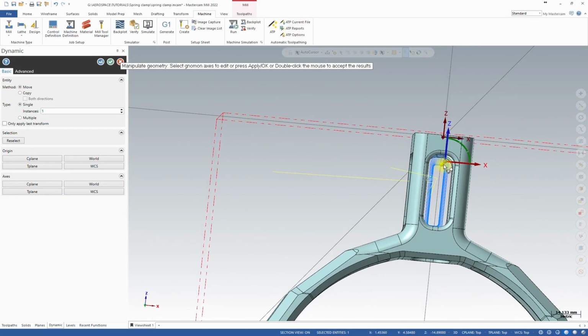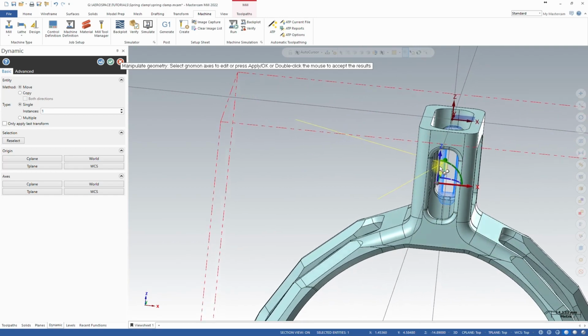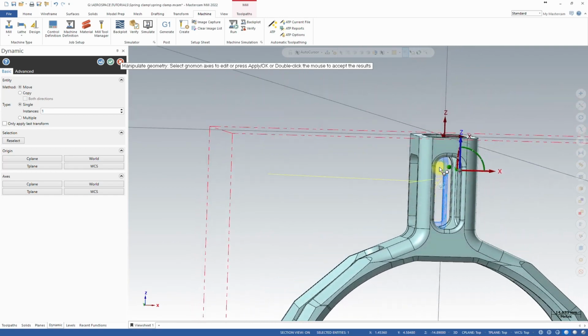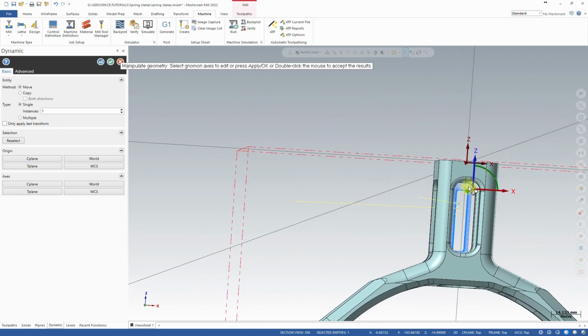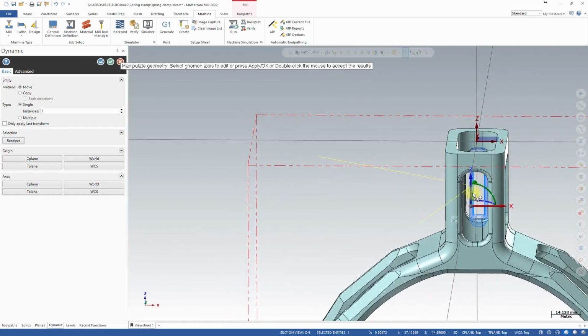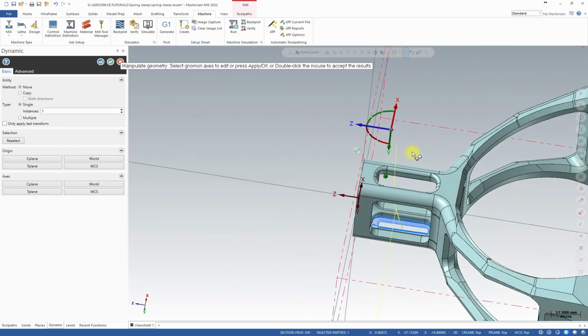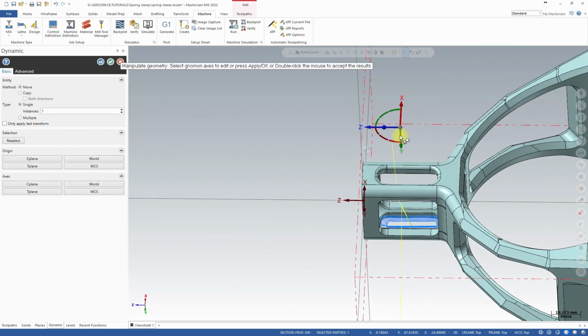So now if I grab this point with my third mouse button, I can use this point to aim around, track it around the machining surfaces to get a feeling how much motion, how much rotary and tilt action I'll get during machining. And I'm a bit too high, so I'm going to move that as well, maybe 10 mil.